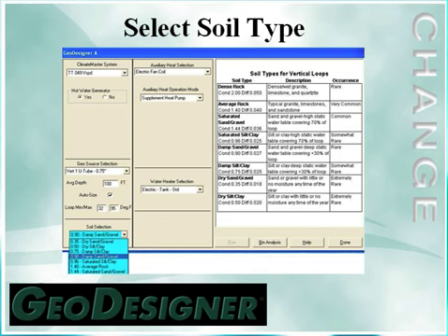32 to 95 are typical minimum and maximum temperatures that we use to design the ground loop system with. The unit will run outside of those parameters, but if we stay in that range, that'll give us a little extra safety factor if we get some extreme weather, like we saw this summer with some extreme high heat, and then sometimes in the winter some extremely long cold temperatures.